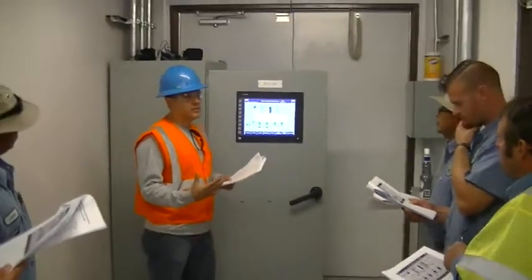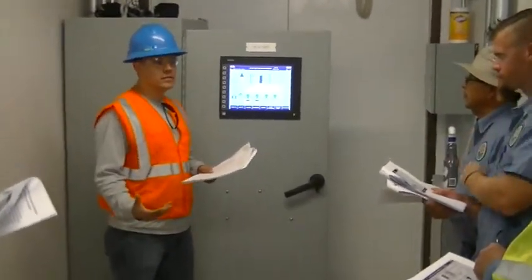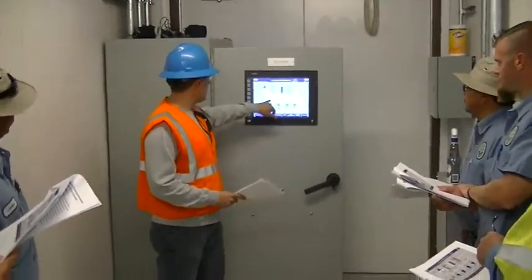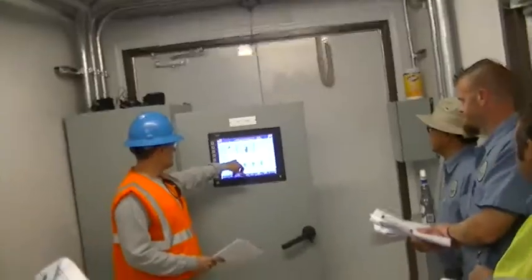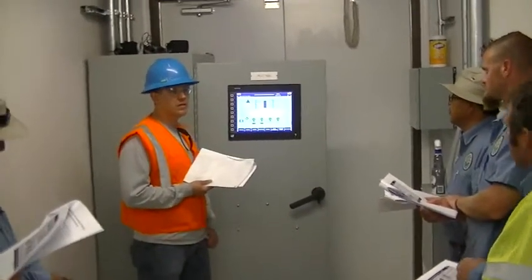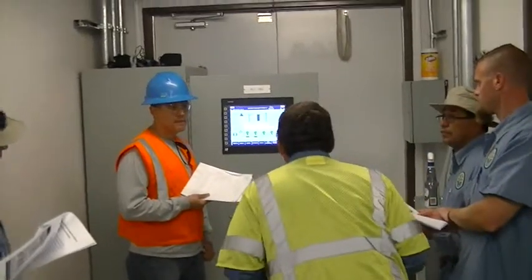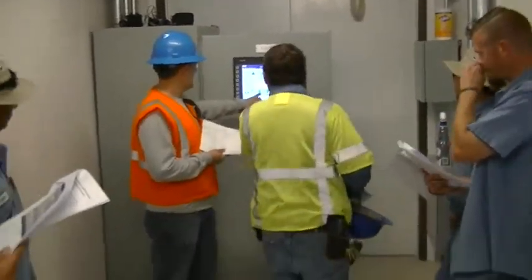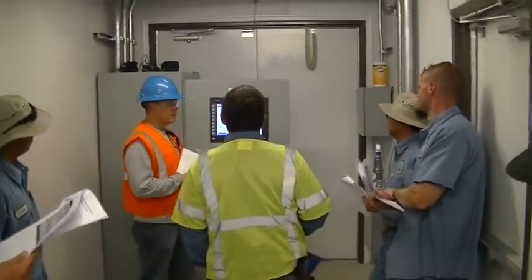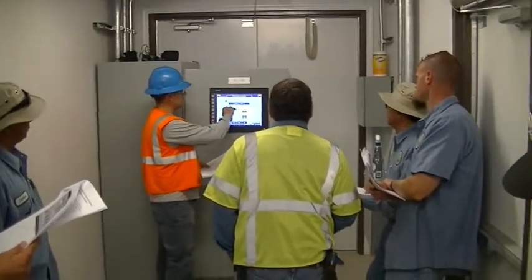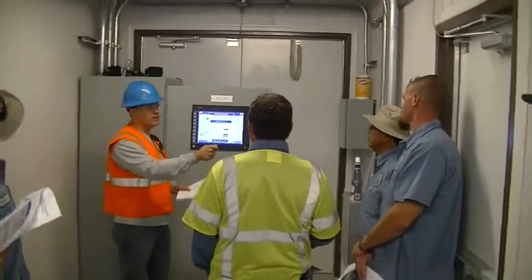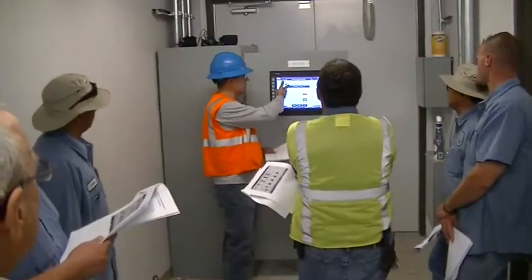Now called is when you're called to run, but you're not getting your run signal yet. Does that show on a screen then too? Yeah, that'll show right here. Basically, it'll tell you what condition it's in, and the color of the motor itself will also tell you that. If you click on it, it'll give you the motor pump control, and it'll also tell you what condition the switch is out there. It's either off, or local, it'll be local.